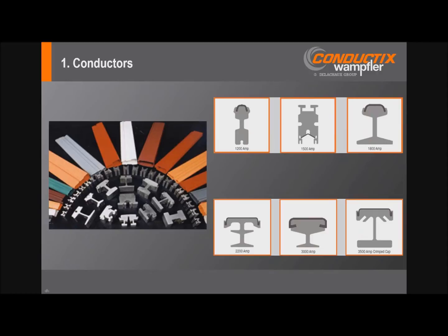And the conductors can be easily cut to length and curved as needed for installation. The relatively low cost of aluminum extrusion dies really makes this an easily adaptable and cost-effective material to produce in fairly low volumes in a wide variety of profiles and configurations. The conductors are shaped for use with either a guided collector, typically smaller systems in AC, like the center one here, the 1500 amp, or a pedal-type collector shoe for higher current capacity and typically DC applications.